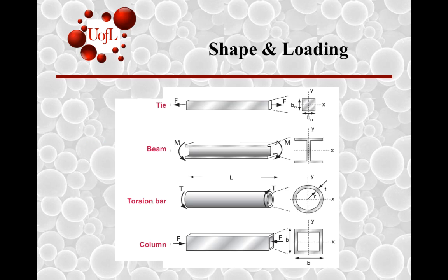So going from table 9.2, one thing that has to be reinforced that we knew from strength of materials classes is the fact that in addition to the shape, the loading matters as well. And so for certain loading conditions, certain shapes are more efficient than others, which is introduced in this case for a tensile geometry for a tie as opposed to a column which is under compressive strength in the bottom, and things related to bending or torsion in the middle.